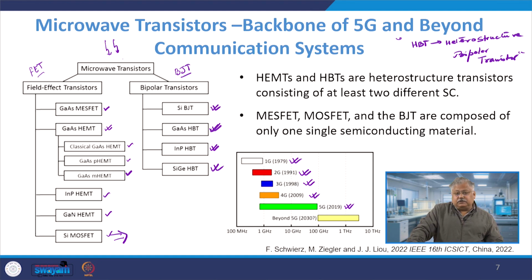The advantage which we get is of course a high sampling rate, therefore communication is much easier and faster, but sustaining such a high frequency without compromising on the power is the main basic challenge for any microwave transistor based design.